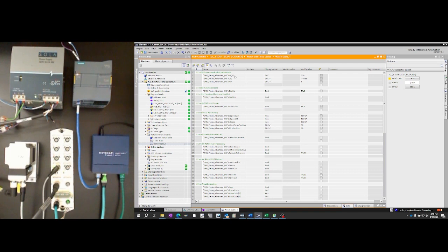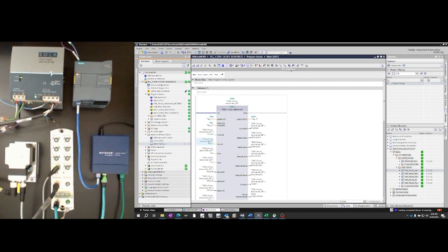The hardware ID, which you can see here on the advanced function block, right next to ICAP and IPort, is an identifier that tells you which device we're trying to communicate with. There are 2 types of hardware identifiers, an IOLM for master and an IOLD for device. If you want to communicate with several devices on one MURR Remote IO block, you can do so by using the hardware identifier IOLM. This is only available for Pro modules.